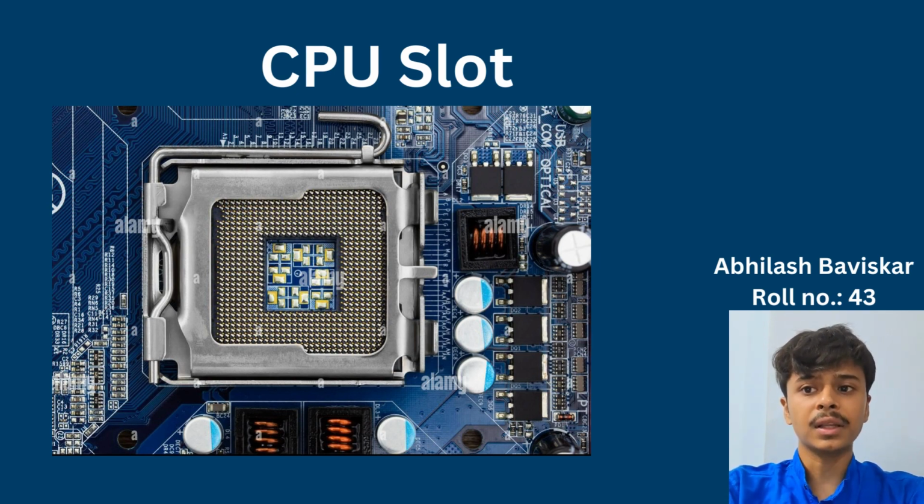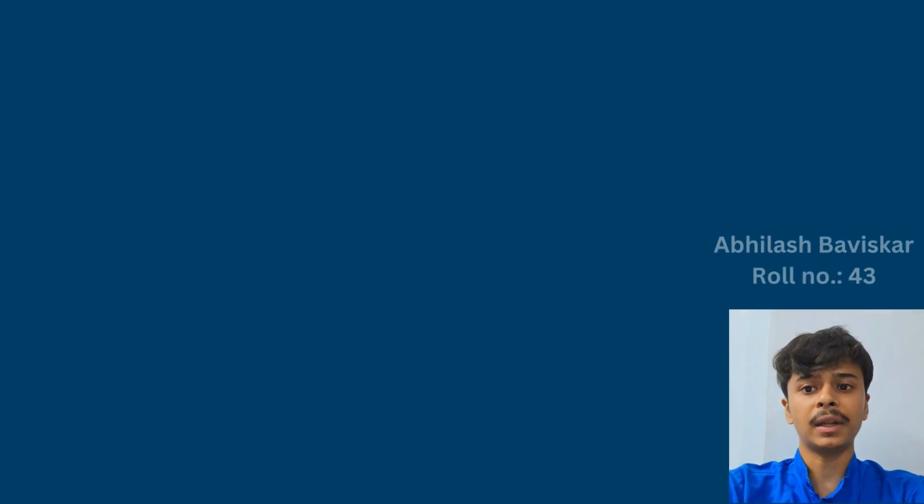Beyond the mechanical aspect, the CPU socket also serves as an electrical interface between the CPU and the rest of the system. It features an intricate array of pins or LANs that align with corresponding contacts on the underside of the CPU. These pins or LANs establish electrical connections, enabling the transfer of data and power between the CPU and motherboard circuit. The number and layout of pins or LANs on a CPU socket depends on the specific socket design and manufacturer. Each CPU socket type supports a specific CPU family or generation with unique pin configuration tailored to fit the corresponding CPU's contact pattern.